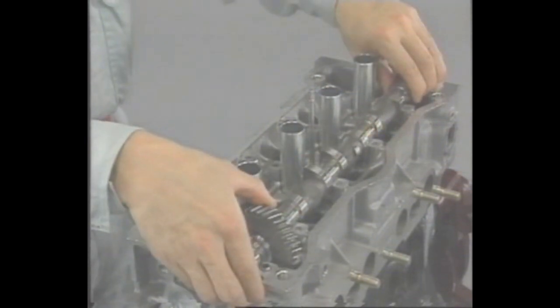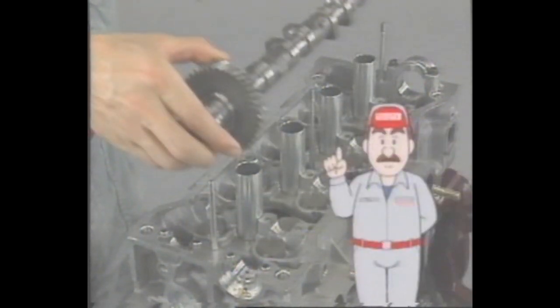When removing the number 3 bearing cap, loosen the bearing cap bolts little by little, carefully, in several passes, as with the intake camshaft bearing caps. Now the camshafts have been removed. During these procedures, be careful not to apply excessive force to the camshafts or damage the thrust portion on the cylinder head side with a tool or other object. This could cause problems such as camshaft seizure or breakage after the engine is reassembled.